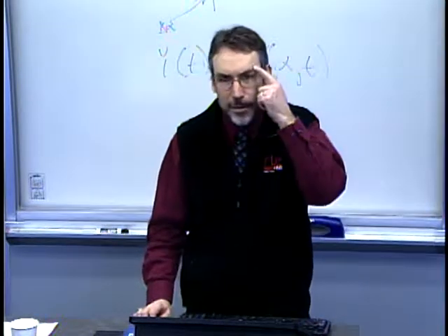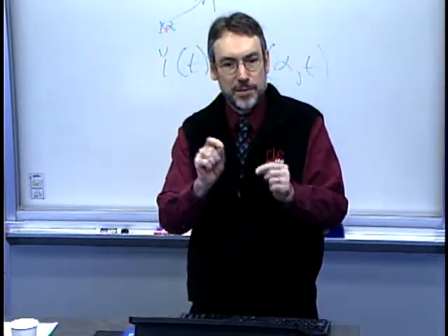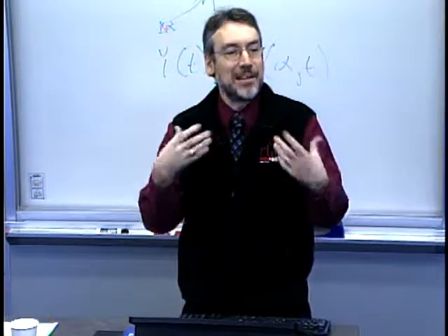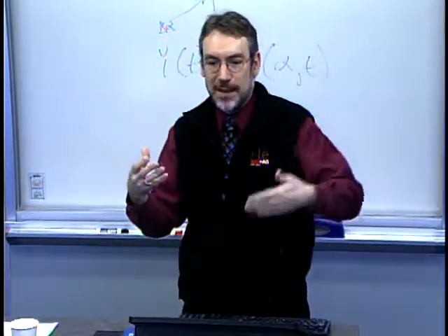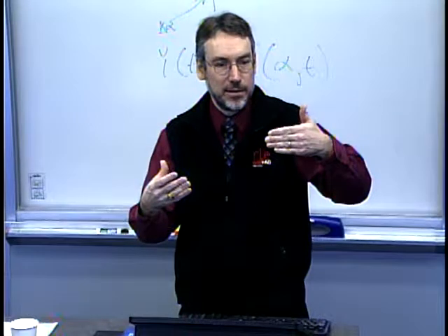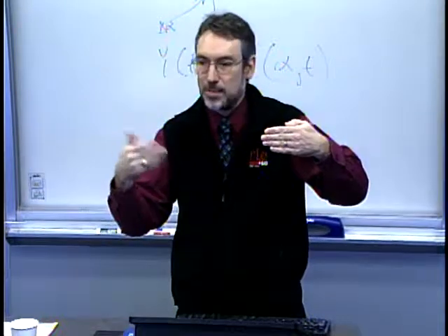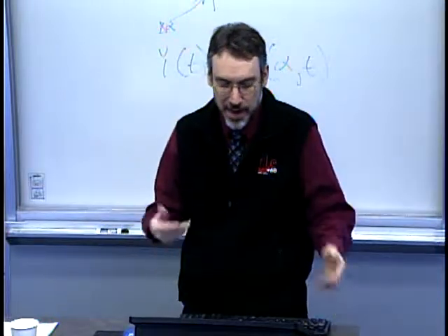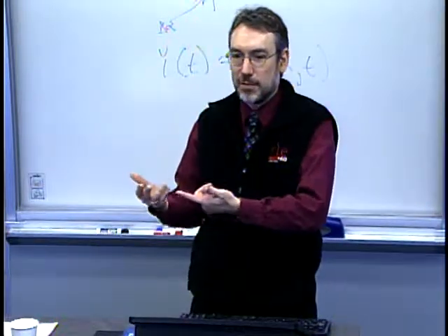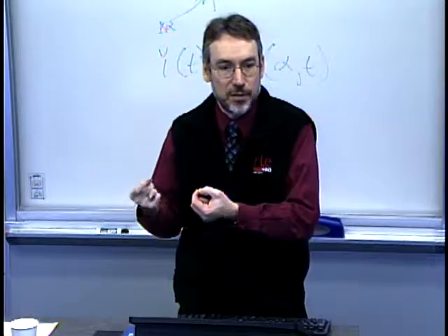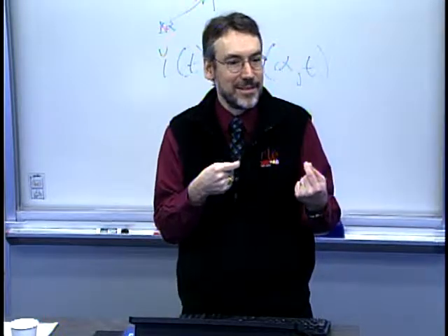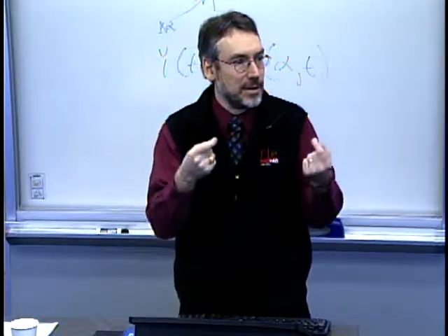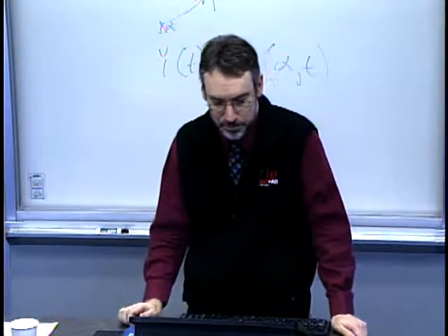So I'm already starting to think, okay, I can have a very simple additive empirical model that has a delta effect due to the material type. It's a binary choice, or a binary coefficient, depending on that. And then an additional component is a function of thickness, and maybe that function of the thickness is independent. That delta from a mean is independent of material type.